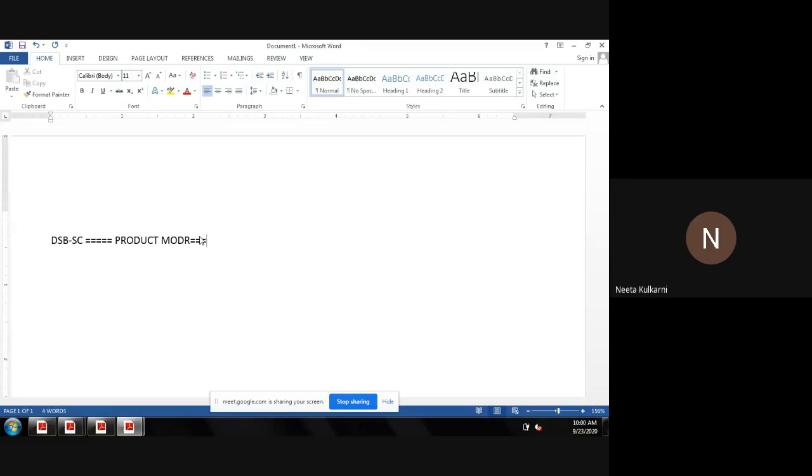म्हणजे प्रोडक्ट मॉड्युलेटरला काय म्हणतात आपल्याला आउटपुटला DSB-SC ला नोटेशन वापरलेलं आहे S of T into carrier it will be noted as C of T. म्हणजे इथं आपल्याला मिळतो आपला ओरिजिनल AM सिग्नल. मग इथं जी डायग्राम आपल्या सिलेबस मध्ये आहे त्यामध्ये काय वापरलंय ह्याच्या आउटपुटच्या पुढचा ब्लॉक कुठला आहे लो पास फिल्टर. The output block, it is low pass filter. So this low pass filter will demodulate this AM signal and we are able to get the output of low pass filter.